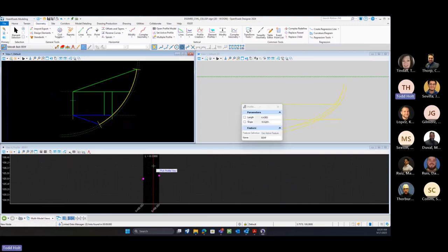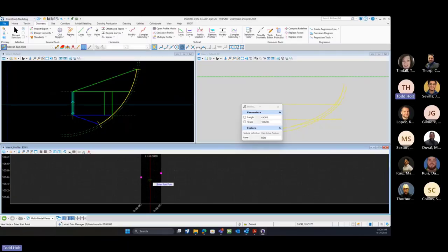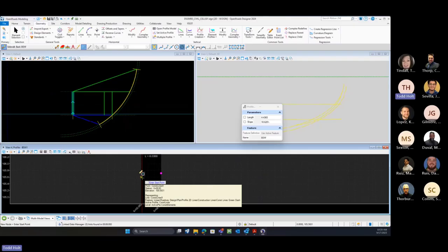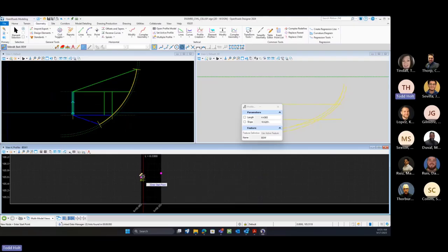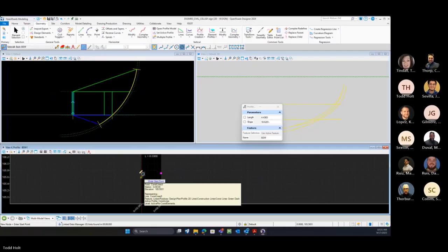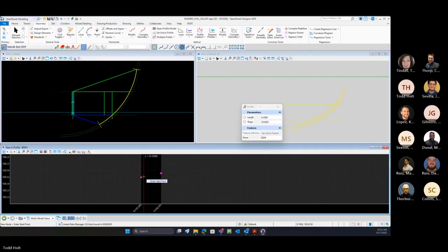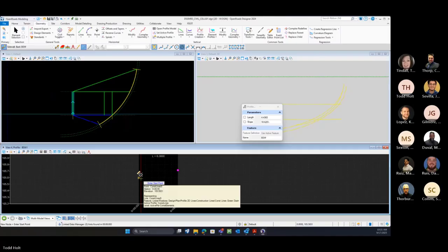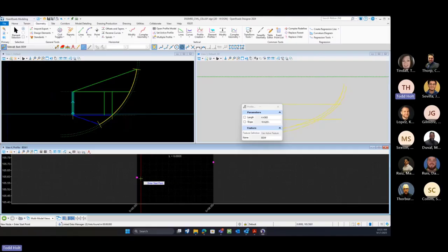And in that profile line between, I'm going to pick my profile view. And in the profile view, a trick in here is I don't want to do my tentative snap. So I don't want to come in and do that, my mouse button. I want the software to do it. So I'm just going to get close to that origin of that point. And then snap.